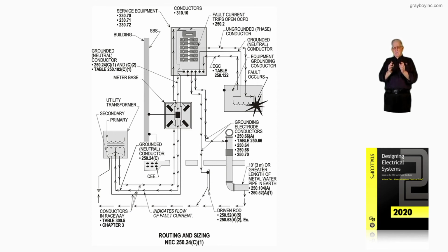But if for any reason the metal conduit did not pull the 90%, but only pulled 70%, the equipment ground now would pull 30%, and it would pull any amount. Say that you had 100% restriction, then the equipment ground would pull 100%. So 250.118 allows redundant grounding in that manner, I call it.